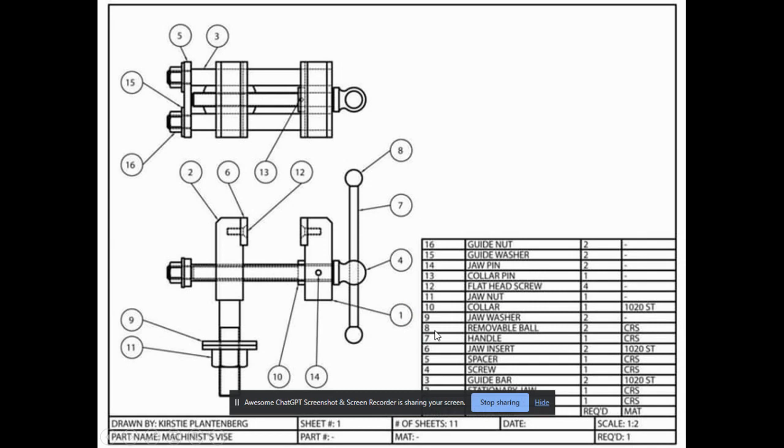So this is also another assembly, but if you realize, we have two drawings now. One is representing the front view, the other is representing the top view. Now the reason is that part numbers 16, 15, 5, and 3 cannot easily be identified in the front view, but you need to reorient it in the side view to be able to get them. All right. So this is where the two views become necessary, if and only if there are some parts that need to be reoriented to be shown or easily identified. If not, a single view is okay.